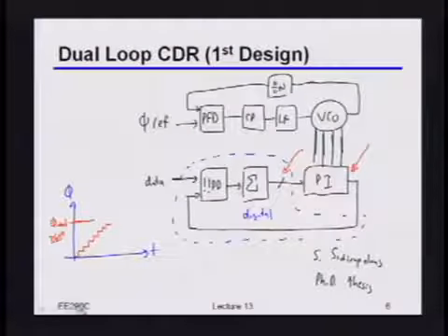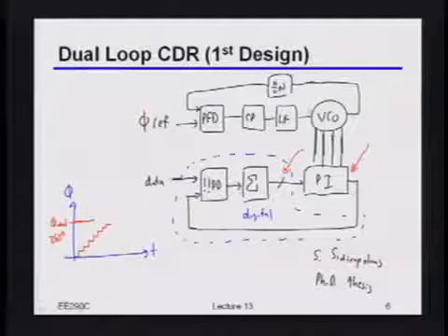And the basic idea is the following. What you essentially say is, okay, look, let me use some sort of phase lock loop that uses a quote-unquote good reference clock just to generate the right frequency to begin with, or something that's at least close to the right frequency, okay? So if I do that and I really do have a clean reference, then I can make this loop bandwidth for this PLL whatever it needs to be, based upon the noise I have on that reference versus the noise that I would have really had in this VCO. And again, that would tend to be something fairly high if you actually had a clean reference available, okay?